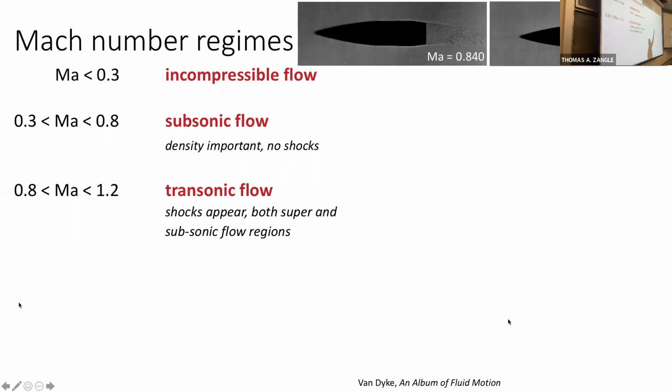So what's happening is that even though the characteristic velocity is subsonic, the flow locally in some of these areas around these corners is accelerating to the point where right there, it's exceeding the speed of sound, and we have a little shock wave forming. You see that? And so even though the characteristic velocity is subsonic, we can still have shock waves within this flow.